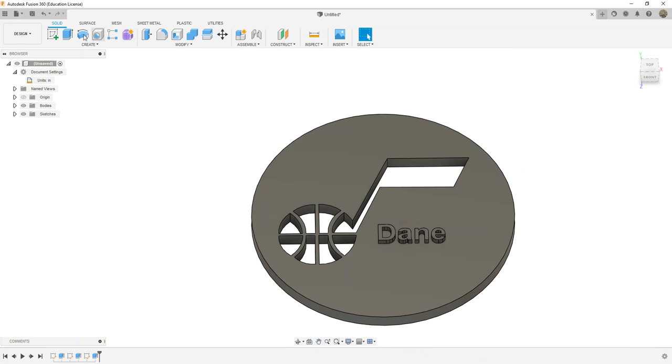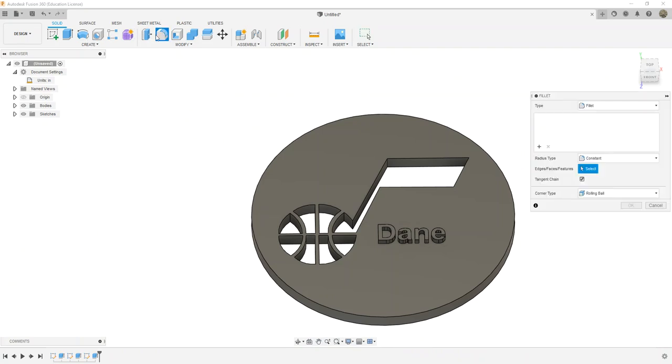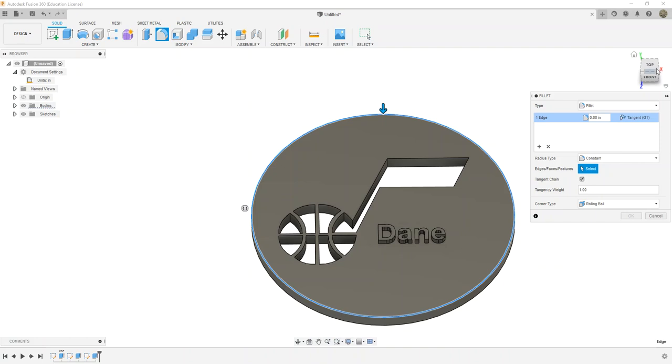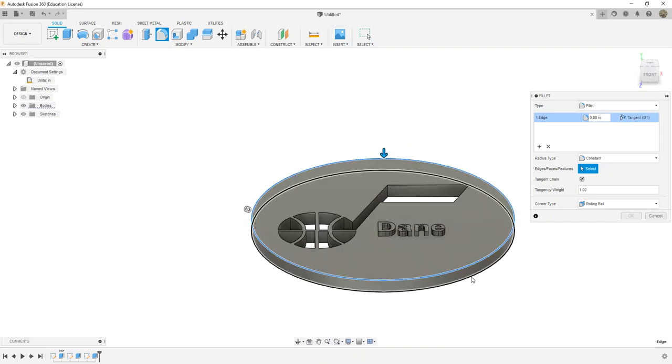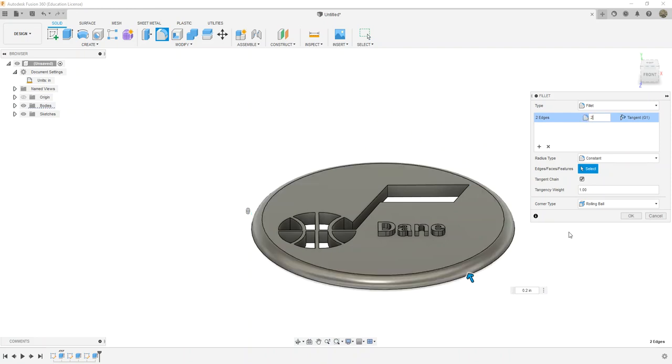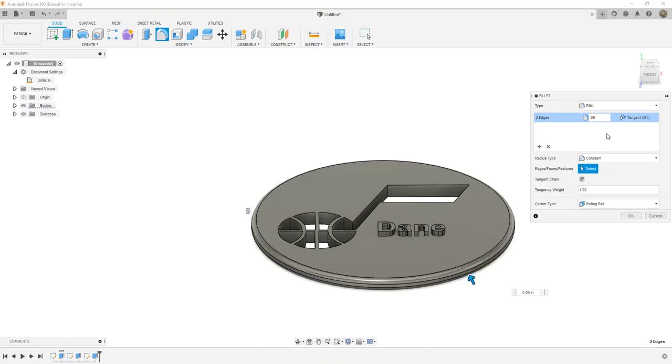Okay, and then I could go through and I could fillet the edges. Fillet tool, clean it up that way. And you can type in numbers here until they work. If it's not working, you need to make a smaller number. See, I'm doing 0.2. That's like 1/4 of an inch. Or maybe 0.09, depending on how thick it is, you just adjust this number to what looks good to you. 0.1 actually might look pretty good. 0.15. So you can play around with that.